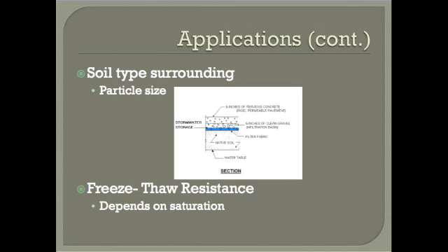Usually, the rapid draining prevents the profile from remaining saturated during the freezing process. However, if a large amount of water is expected in a frequent freeze-thaw environment, an option is to increase the base layer. Now, the increase in size of the base layer adds a larger void content and decreases the likelihood that the pervious section of the concrete will remain saturated. You could also introduce a perforated pipe to carry water away from the soil with low permeability into soil with a higher permeability.